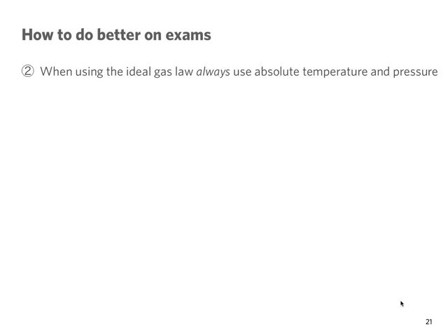Another point on how to do better with exams. When using the ideal gas law, always use absolute temperature and pressure. Always absolute temperature and pressure. So make sure you check if you have a problem and you're given a temperature, that you convert that to absolute values. You're given a pressure, you ask yourself, is this absolute or relative? And if it's not, you need to convert to absolute before you plug it in your equation, okay? For example,